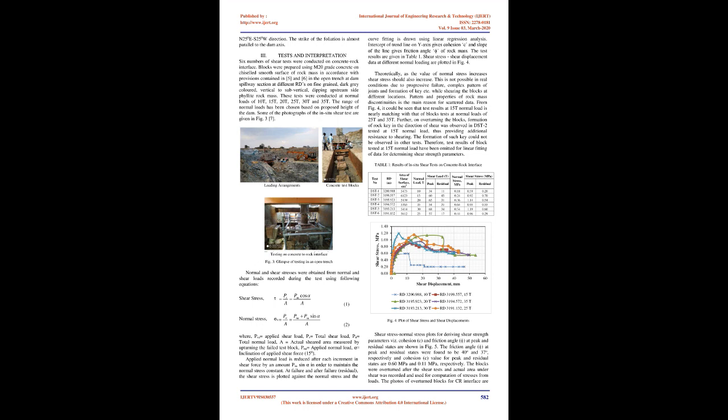Theoretically, as the value of normal stress increases, shear stress should also increase. This is not possible in real conditions due to progressive failure, complex pattern of joints and formation of key etc. while shearing the blocks at different locations. Pattern and properties of rock mass discontinuities is the main reason for scattered data.